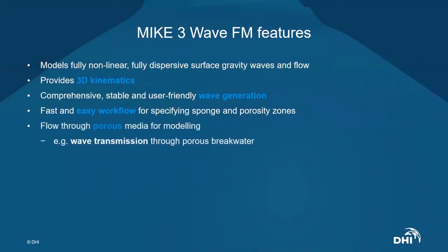We have this comprehensive, stable, and user-friendly wave generation interface where you can easily specify different wave generation zones. You could have multiple wave generation zones, allowing you to easily introduce both sea and swell waves coming from different directions. We also have a fast and easy workflow for specifying sponges, sponge coefficients, and also porosity zones.